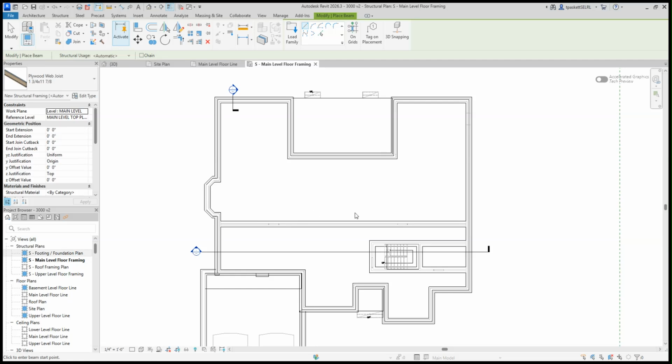And you want to keep a copy of this. So sheet 6 here gives us the dimensions of each of the different price series that you can purchase. They range from 9.5 inches to 16 inches. You can custom order 24-inch depth TGIs. They're very pricey, but your house is very, very solid at that point. And what you're looking at here is the thickness of the parts. So this little part in the middle, that's the web. It's almost always 3/8 of an inch, and it's usually out of particle board.